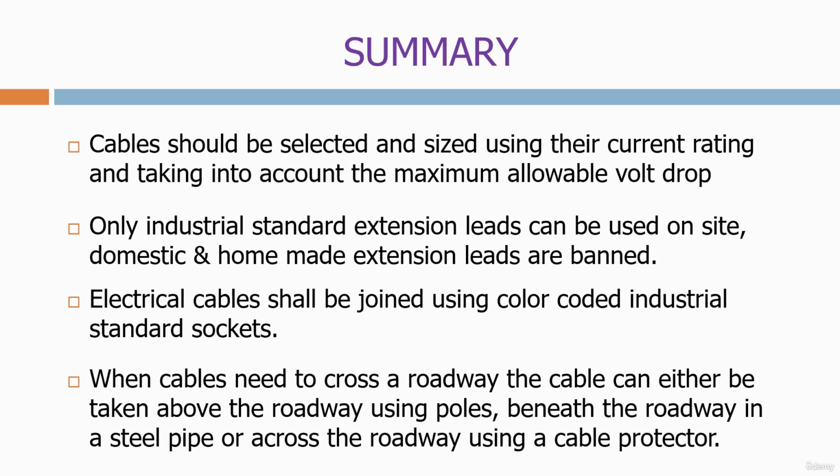When cables need to cross a roadway, the cable can either be taken above the roadway using poles, beneath the roadway in a steel pipe, or across the roadway using a cable protector. You are now nearing the end of the course and should have a good understanding of electrical cabling and the other elements that go into a site electrical network.